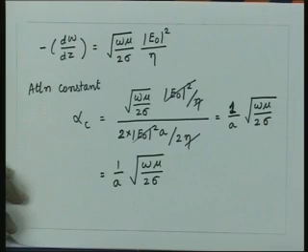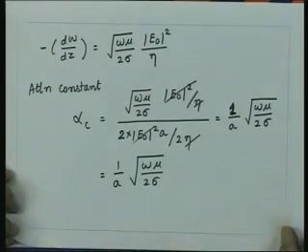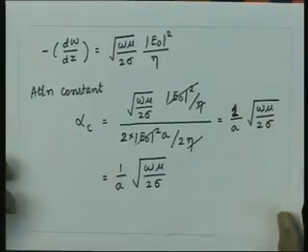So whenever we have these guiding structures, invariably you will see the effect will be like a low pass filtering and the signal will get distorted. That means there will be blurring of the sharp edges in the signal in time. Signal gets smoothed out because you get a low pass filtering action because of the loss behavior of this waveguide. So in conductor loss in general, one can say that it varies as a function of frequency, and as we increase the frequency we get the higher loss, right, for the same waveguiding structure.